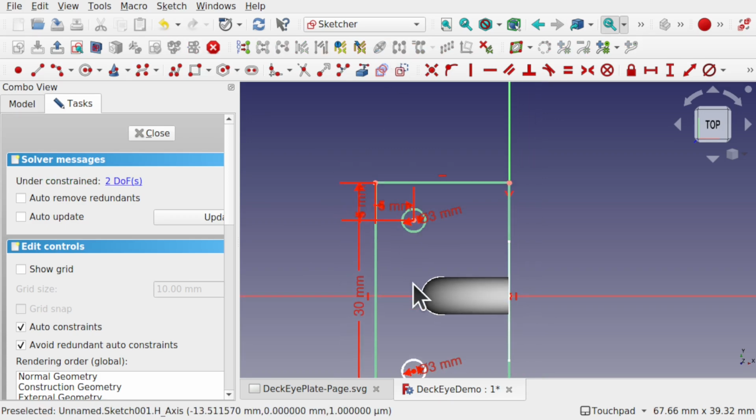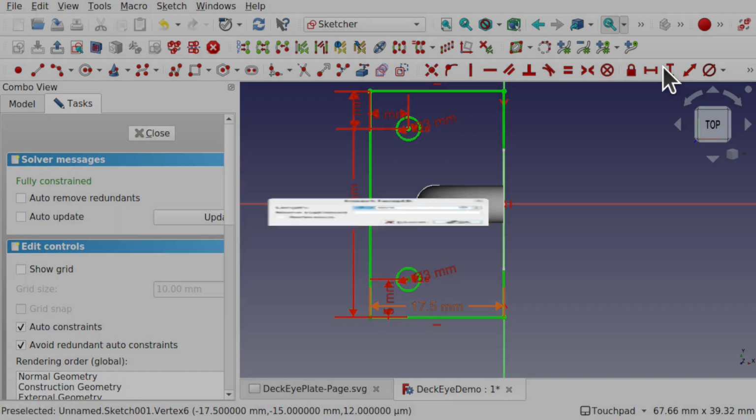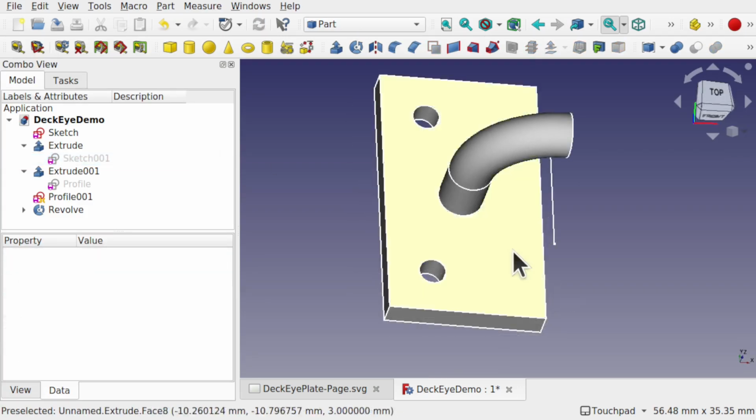Symmetrical across there, and we'll keep those in line, that one and that one in line, and we also need a height to finally constrain this all down of 5mm and close that. That creates those holes. So now we've done that, that's joined these all together.